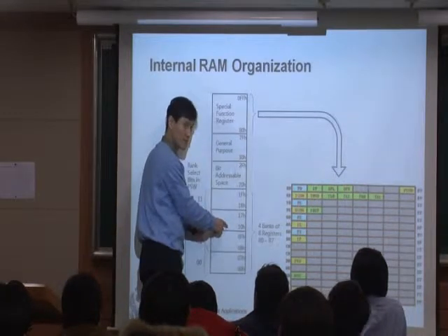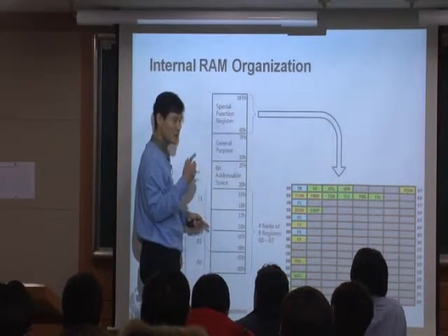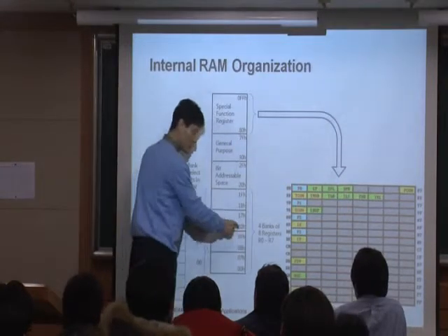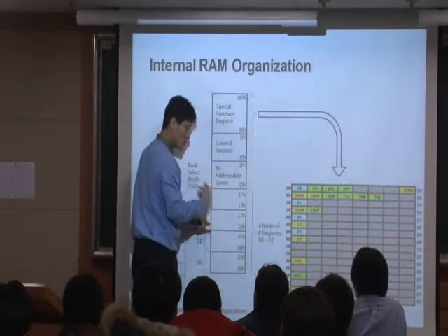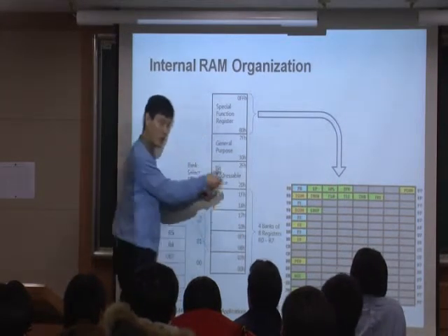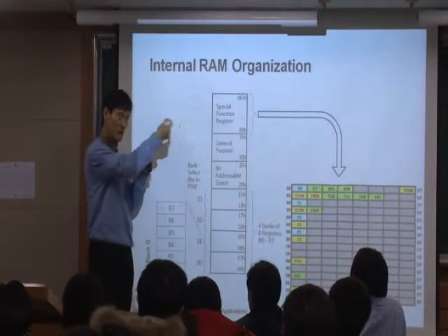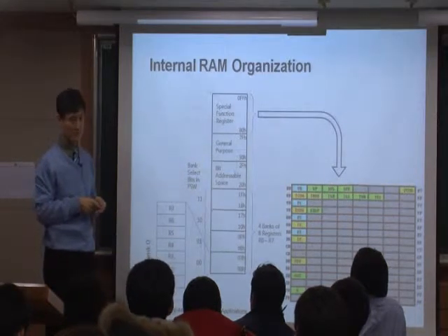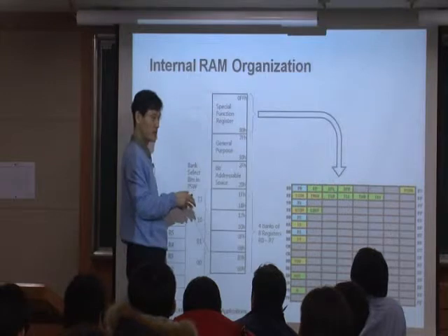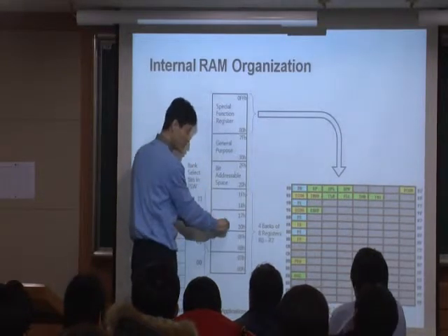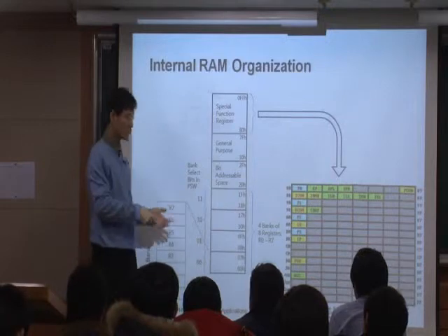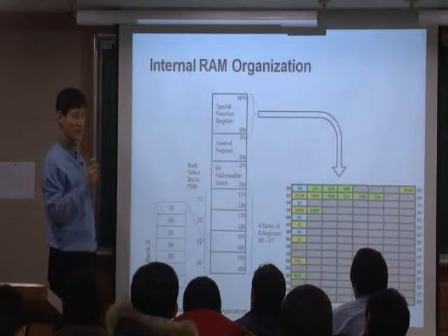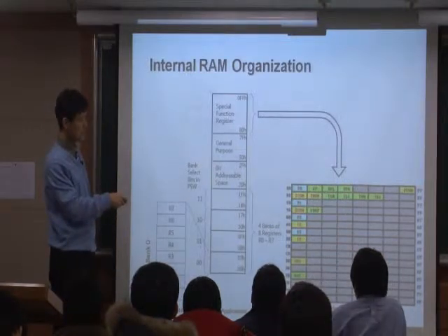That's not possible. If you really want to do that, you first read this whole byte, because this whole byte is at 10H. So you use this address, 10H, and you read the whole byte, and then you take only the bit you need later. That one you can do. However, from the microprocessor perspective, you cannot simply read only 1 bit, because an address is associated with a byte. However, in this part, you can do that. That's what it means: you can do the bit addressable space.